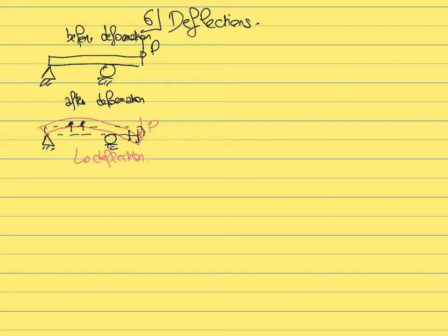due to the fact that the straight line, that's what the beam used to be, now becomes a curve with a certain curvature. So the deflection will correspond to a lateral displacement of the beam, where at each position along the x-axis, each point M that is located at a given position x will either move up or move down due to the bending. And so to quantify the extent of bending, what we typically use is the elastic curve of the beam, where the elastic curve is the deflection curve.